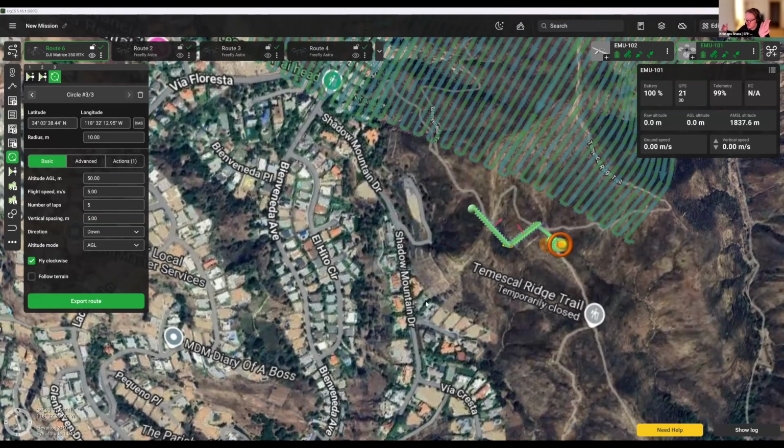If you just want to have some very basic 3D model, you would just do a horizontal flight, and that's it. And you can manipulate the camera angles in different ways. You can, for instance, instead of having the 90-degree camera angle, use something like 70, and with that, you can still put all of the images in some photogrammetry software such as Reality Scan, and you can get a good result. However, if you really want to capture good data on the facade, and if that's important, that's when you need to do the vertical scanning.